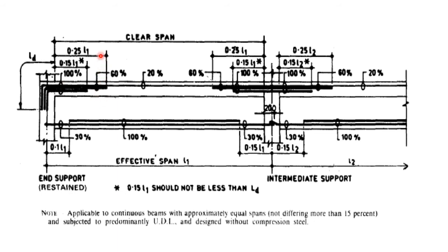If I take a section at a distance, we will have only 60%. It is hanger bar and negative reinforcement. If I take exactly at the middle, I have only 20%, that is just the hanger bar. The same thing will be applied here also. Whatever length you provide from the face of the column till here, all of this will be the development length Ld, which is equal to 47 times the diameter.